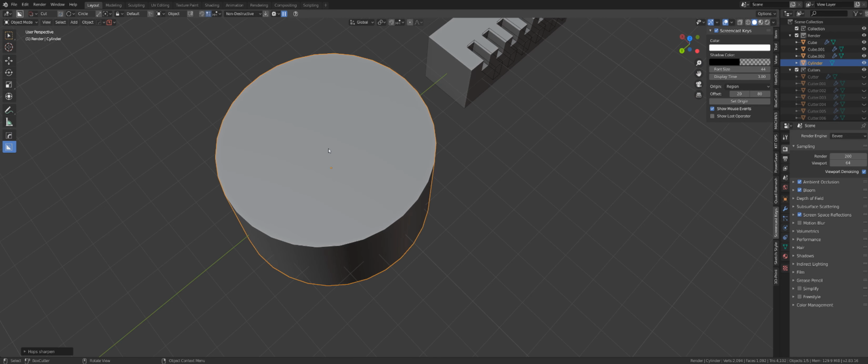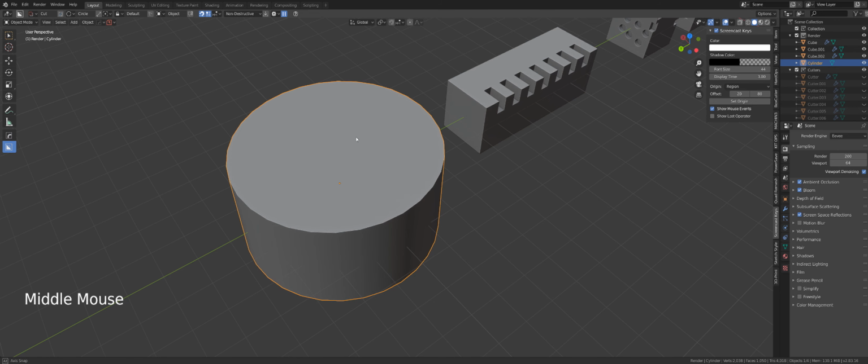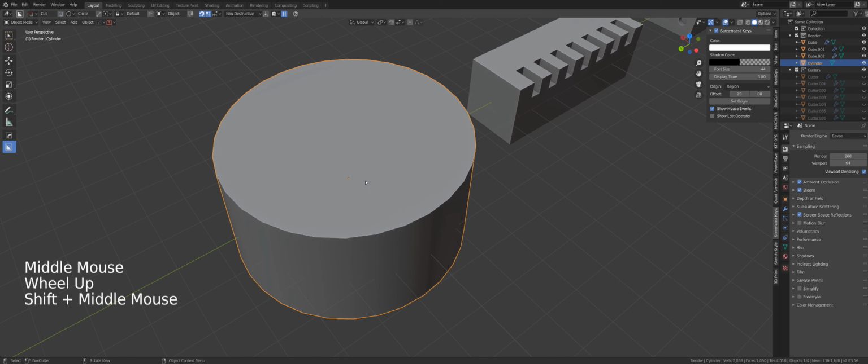But there is more. Let's create a circle somewhere more or less in the middle and press V twice. Now I have a circular array. But you can see it's not in the middle, so that's a bit of a problem. So how do we solve this? Well, you could go to this option in here, which is a snap grid. And if you turn those two options on, you're going to have the snap and grid at the same time.